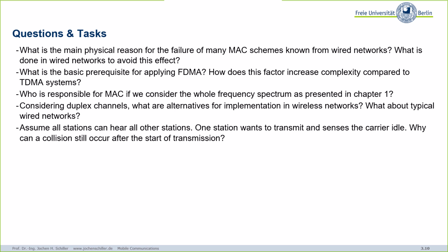So although in today's systems you use different frequencies for sending and receiving, your mobile phone will not send and receive at the same time. Although you send on a different frequency, your own signal is that strong, your receiver is a very sensitive one, and this receiver cannot receive anything, although it's a different frequency, because we do not have perfect hardware.